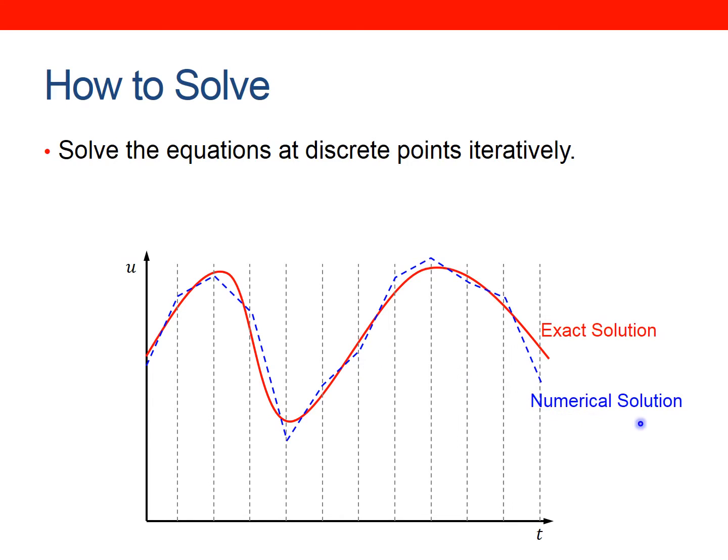So in terms of setting up your numerical solution, you need to be conscious that if you do have quite high gradients in your flow, then you might need a finer mesh, or if it's a highly transient flow, you need a very small time step. But basically the equations are broken down so you can solve at discrete points.